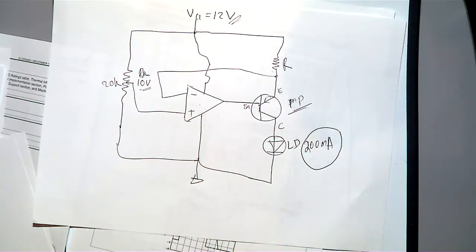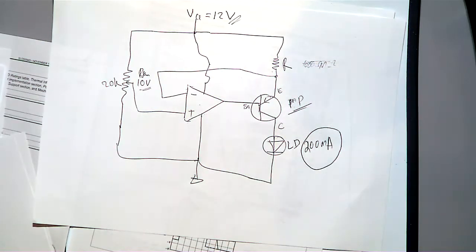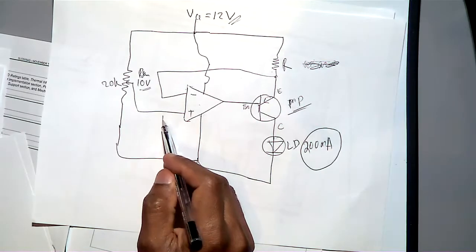Can you design? So what you will be changing? Okay, so when you change the resistance, so what value you need? Definitely you are right. A thousand megohm? No, that means it's open. I think you should change it to 1000 ohms. Okay. So then if I were you, so this is 10 volt because you got negative feedback.